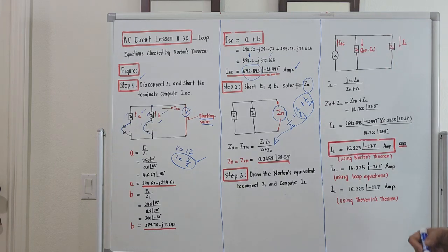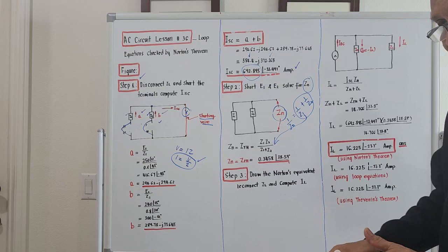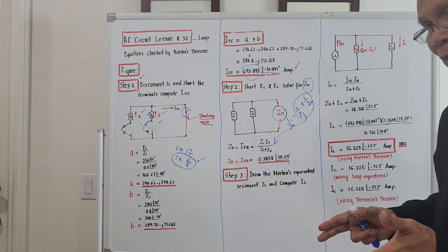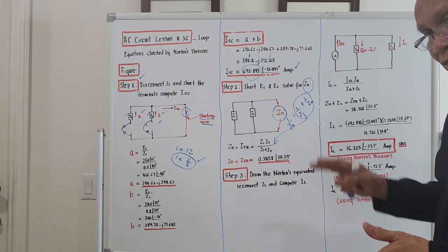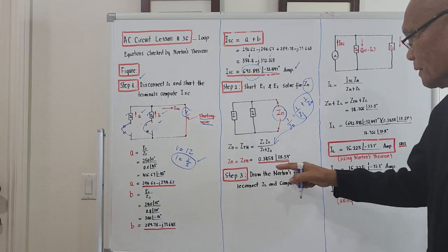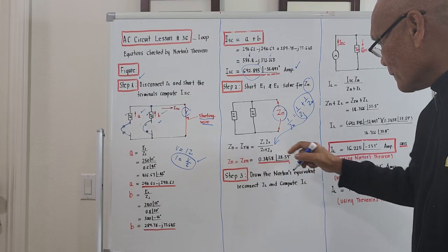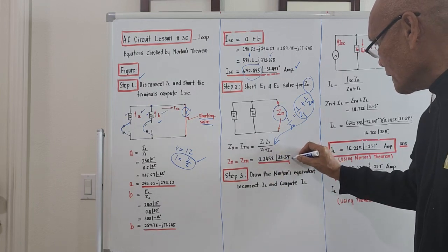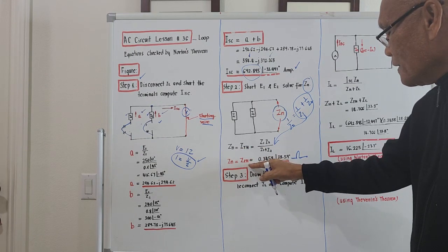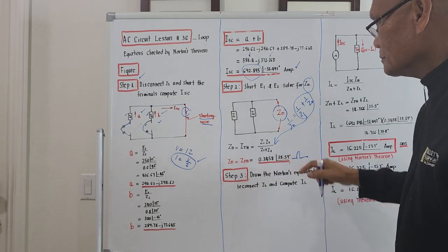The procedure on how to take the Norton's open circuit impedance and also under Thevenin's is the same. So actually, you don't have to compute under Norton's, just copy the value from Thevenin's. Under Thevenin's theorem, the total impedance of Z1 and Z2 is 0.3458 angle 38.59 degrees ohms. They are the same. So for both Thevenin's and Norton's, the open circuit impedances are the same.